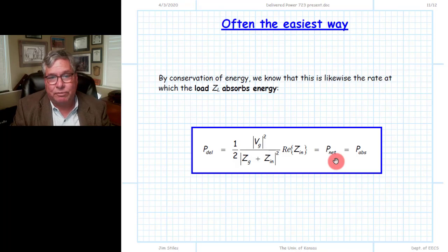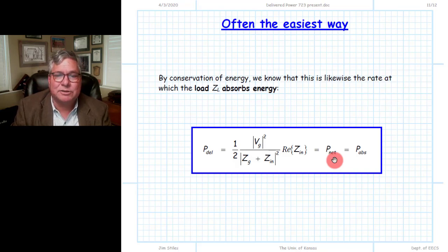You might, and this is more frequently the case, be interested in, let's say, specifically the power associated with the incident wave on the load. And so still this technique would be useful. We can go through and determine the net power flow, which is the difference between the incident power and the reflected power. And if we know the relationship between the incident and reflected power, and we do for a terminated transmission line, simply the magnitude of gamma L squared, then that is the relationship between those two values. We would have two equations and two unknowns.